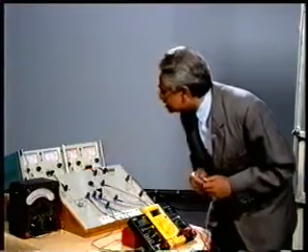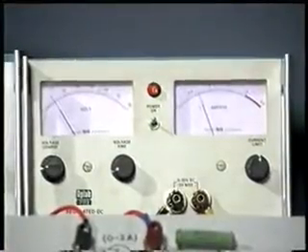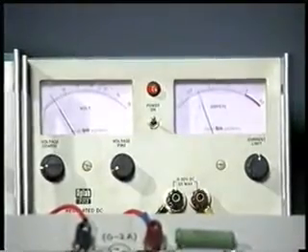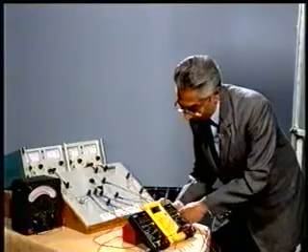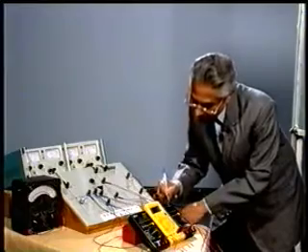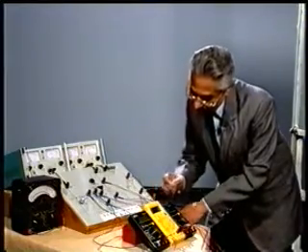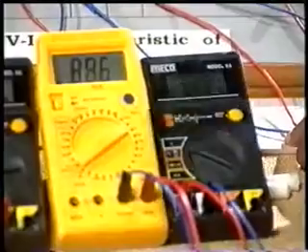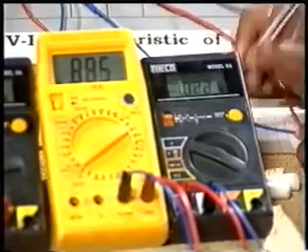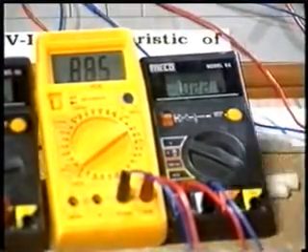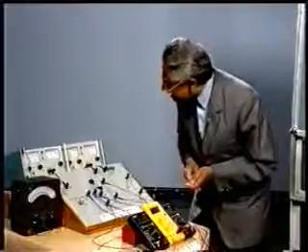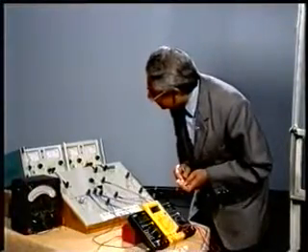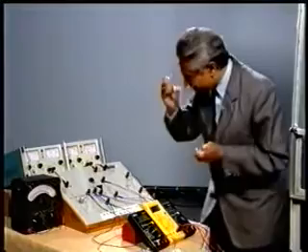So I increase it still and I make it 5 volts. At 5 volts it is a little less than 700, say 675 milliamperes. And it has of course conducted at this point. If you note down the multimeter reading here, it has conducted. So I will take up only those 4 readings, and at 5 volts it has already conducted and it is 675 milliamperes.